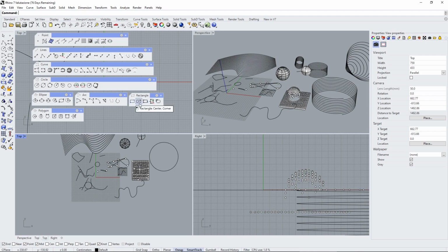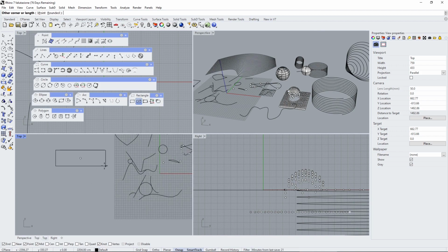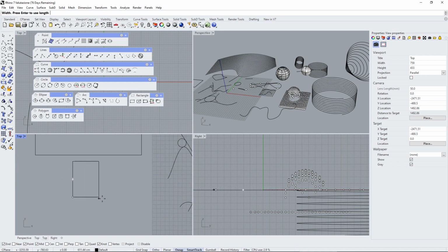Okay, also rectangle is really easy. You can do it with your eyes closed. Click. This one is from the middle. Now I just want to again remark the thing that when you create something, you can change here, and you will usually find all the different options that you find here. So for example, here you can change this to edge midpoint, and you can make it rounded. So this is midpoint. Let's click, and then you have rounded.